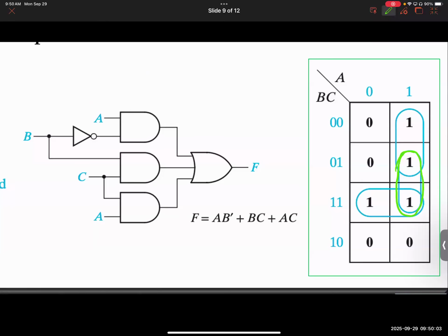If you take more than you need, the outcome will not change. You'll have a suboptimal design. What do I mean by suboptimal? In terms of number of gates, number of inputs, size of the hardware, yes, it will be more, but you'll have glitch-free circuits. Does that make sense?